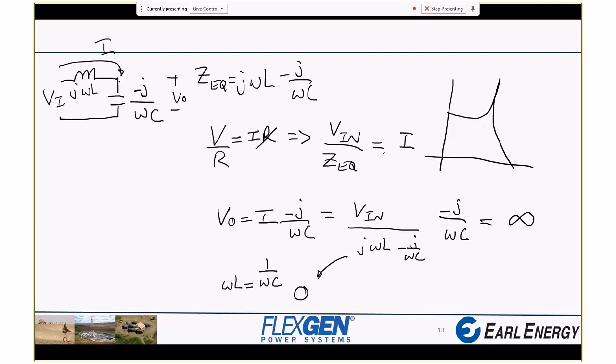This is where parasitic resistances in the circuit actually help us. The parasitic resistance of the wire, the inductor, and the capacitor all limit this to something less than infinity. But it still can be pretty high and cause us problems. It appears in control design, and it appears in loss analysis of multiple parallel converters. So being comfortable with this way of dealing with reactances is helpful.